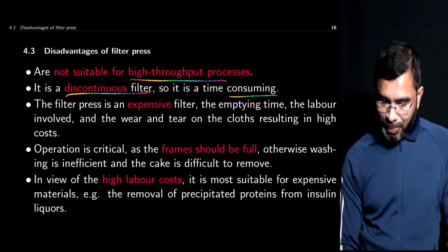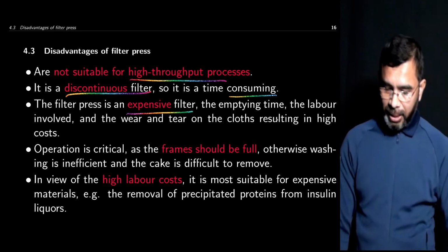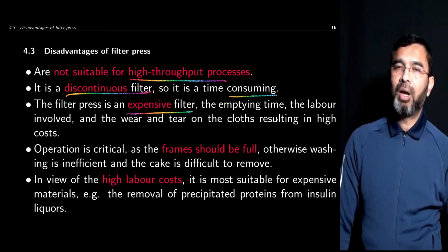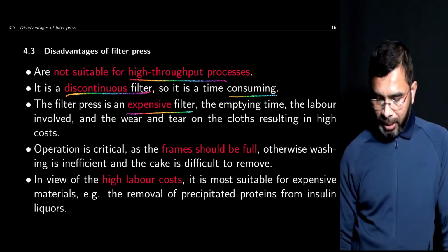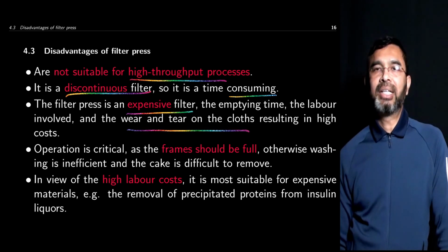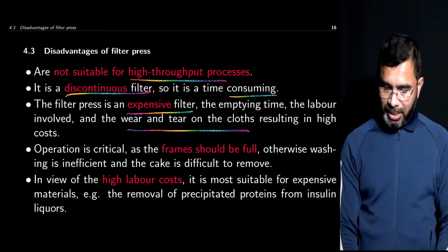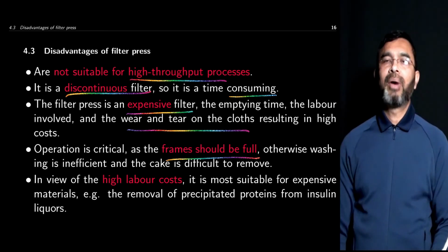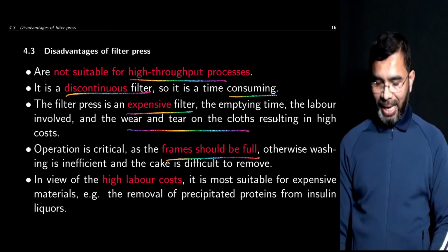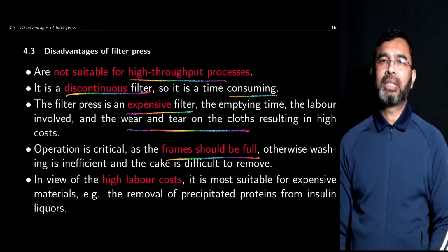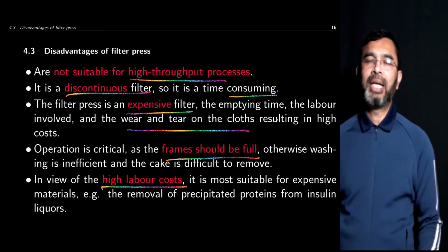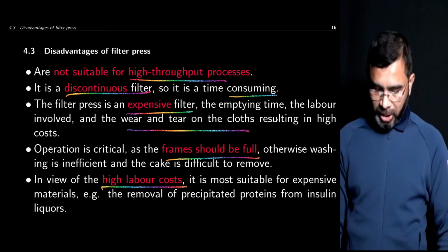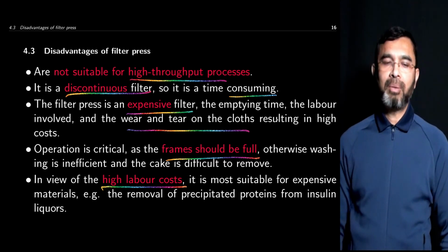The filter press is expensive because dismantling and cleaning will require lots of labor cost, and also because of this dismantling there will be wear and tear of the filter medium. Operation is critical in a sense that frames should be full, otherwise you cannot wash the cakes, so you need to run it for at least a certain time before you can do the washing. And again, because it needs dismantling and cleaning, it's a discontinuous operation, there is high labor cost involved in the